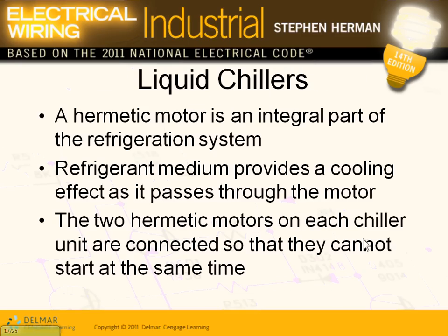Liquid chillers. There are two types of chillers: liquid chillers and the non-liquid chillers. We're not going to go to the other type of chilling. Liquid chillers, you guys are looking at this. You bring a refrigerant, some type of refrigerant compressor, and you chill the water. After you chill the water, you circulate the chilled water directly into an air handling unit. That's the top part, guys.